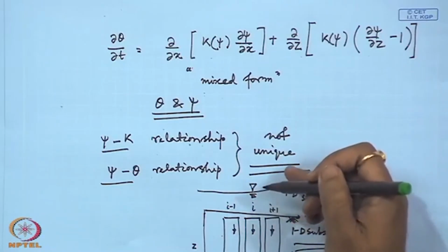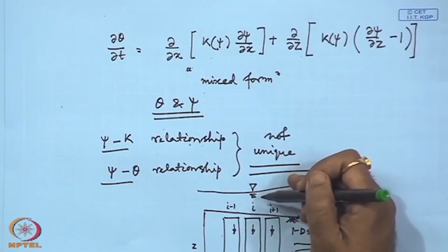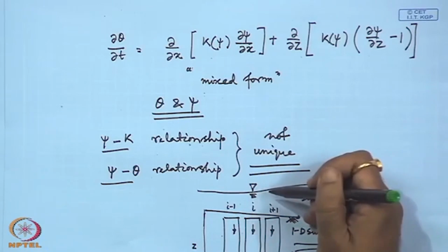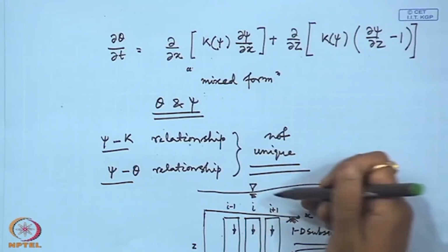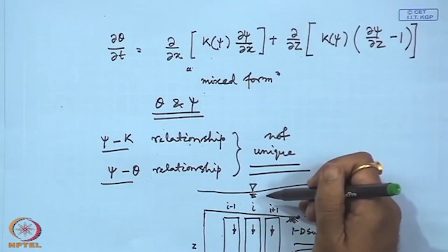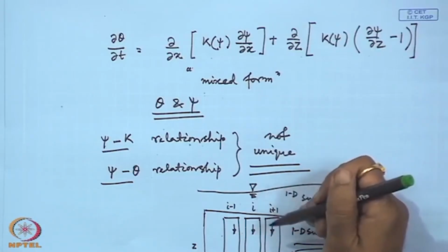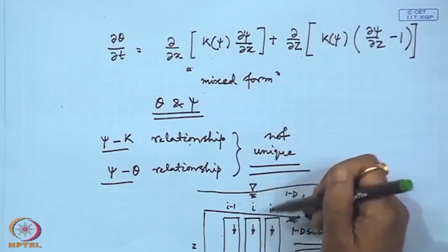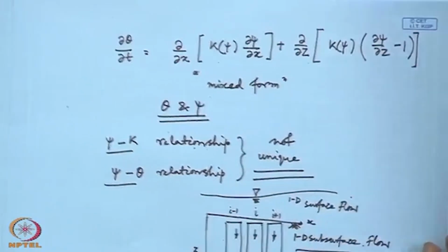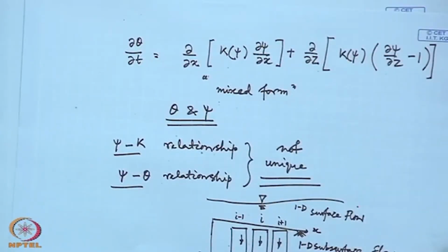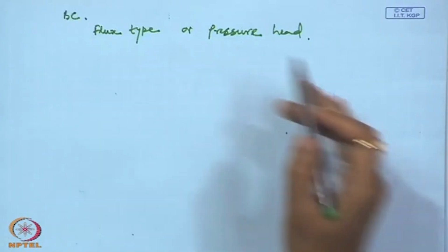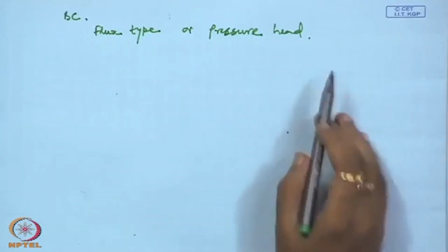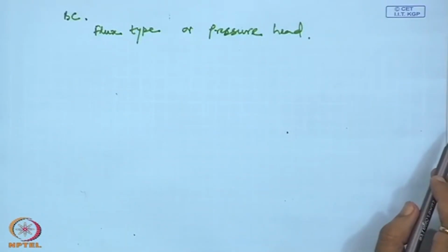We need to solve our surface water and subsurface flow at time level n, then surface flow calculation, and we need to repeat this process to get the convergence, and we need to proceed for future time levels. This subsurface flow equation can be solved using the Newton-Raphson technique.